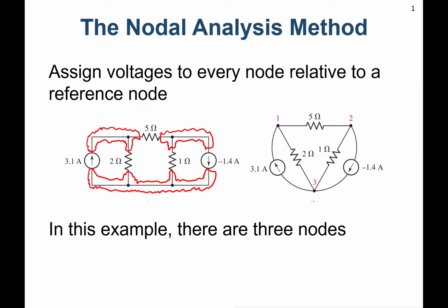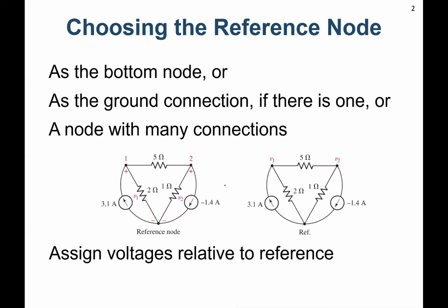It might be zero. A better way to describe it, this is our reference node. So everything is with respect to a reference node. It could be zero, but there's nothing saying that it can't be 100 volts. So the actual voltage, if you were to measure it with respect to ground or reference, could in fact be a much higher potential. But oftentimes in this class, we'll assume it's zero just to make the math a little bit easier. But it doesn't necessarily have to be.